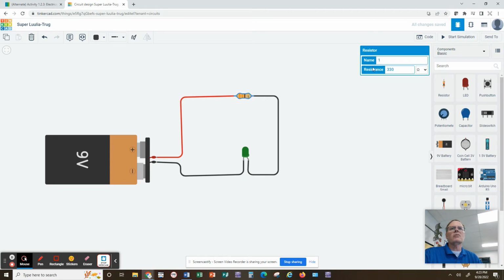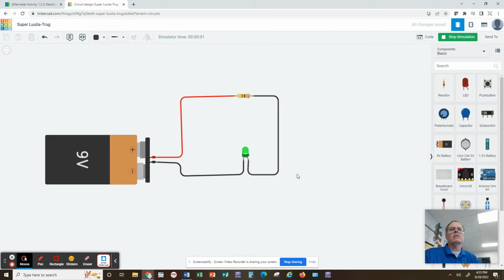I'm going to double click on my resistor, and I'm going to make it say about 480. I'm going to make a little stronger resistor here, right? And then I'm going to start the simulation again. And you notice now the bulb lights up without a warning, because now it's not giving the warning, so it's obviously under 20 milliamps, right?